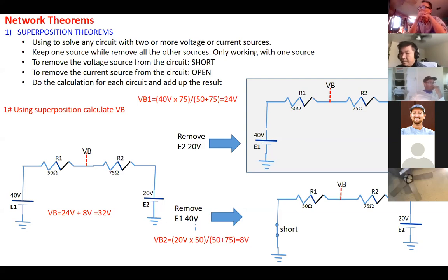They just ask what we use the superposition theorem for. Then the answer will be: when you're solving a circuit with two or more voltage or current sources, then we need the superposition.